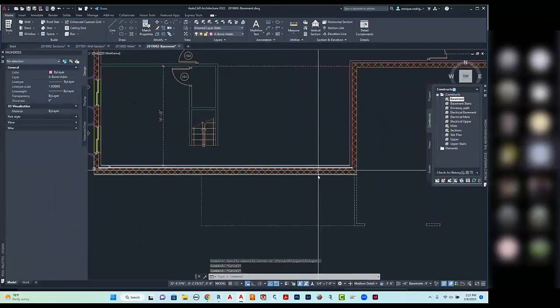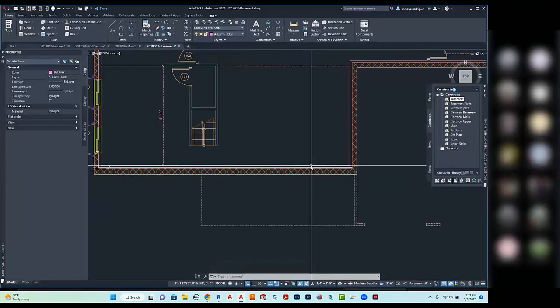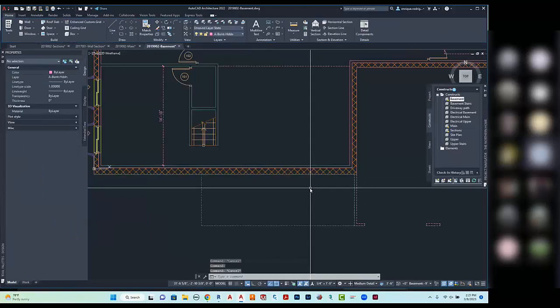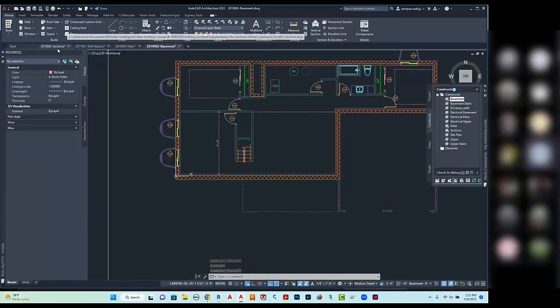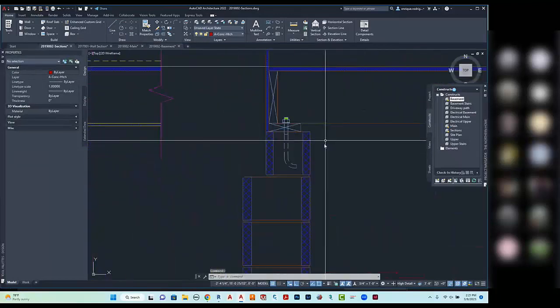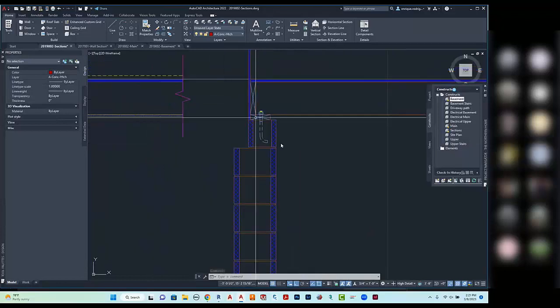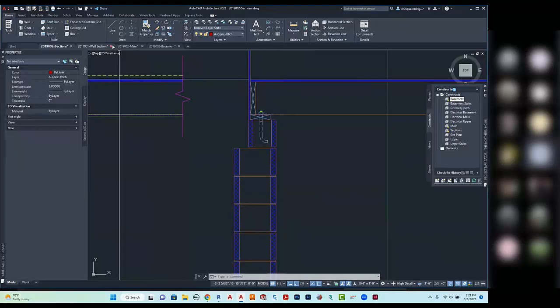This is that block wall that we've been showing you with the 8-inch masonry unit on the top. So inside of that, we actually have a 4-inch stud wall. So let's go back to the wall section, and we're going to draw that wall in section on the inside face.